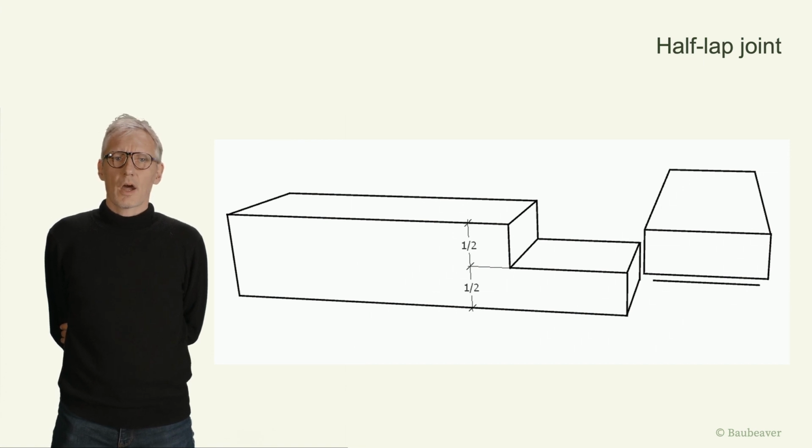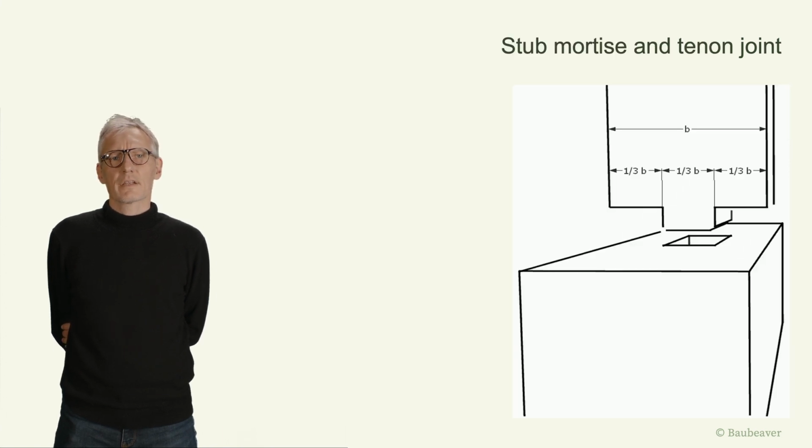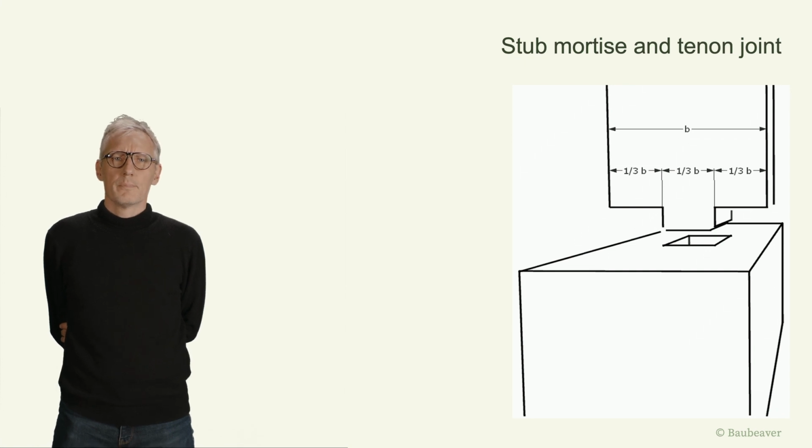When joining the parts, the surfaces are at one level. The joint becomes stable when reinforcing it with screws or sheet metal parts. It is the simplest connection and can be done in a short time. There are different sorts of tenons. A subtenon is chiseled out over the whole width of the beam.